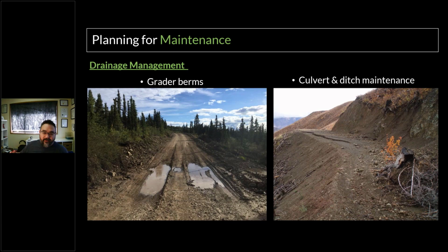sedimentation. I think a lot of people misunderstand predominantly what is behind the creation of potholes on resource roads, and it's not subgrade, it's pumping. The pumping comes from water sitting on the road surface, because you're not in a crown, so the water sits there, something drives through it, it pumps the fines out, makes a big hole. The hole gets bigger and bigger, it's self-propagating. And then graders' berms, they're the enemy most of the time, other than double ditches, which we'll talk about next